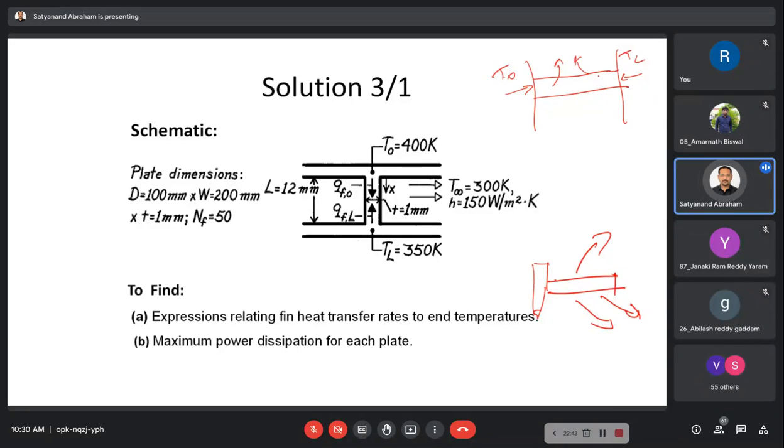We have seen the free end, and the equations we derived till now are for a free end with conditions such as prescribed temperature, the adiabatic condition, convective condition, or infinitely long fin. But this condition doesn't fit any of those cases. So we have to derive the condition here. We have to take a new infinitesimal area over here and start from our basic energy balance. That's what we are going to do.